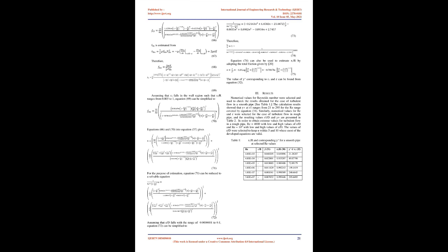The distance y represented by non-dimensional values y/d and y/r decreases with either increase in relative roughness or increase in Reynolds number. The observed trends can be explained by the relation between the variables as presented in equation 31, which shows that y_end is directly proportional to the product of Re and the square root of f, and f reduces with increase in Re before the flow is completely turbulent but always increases with increase in ε/d. Extreme values of y_end obtained, see Table 3, show that y_end can go as low as 6.2, so for a turbulent flow in a rough pipe, there may not always be a buffer zone, 5 < y+ < 30.